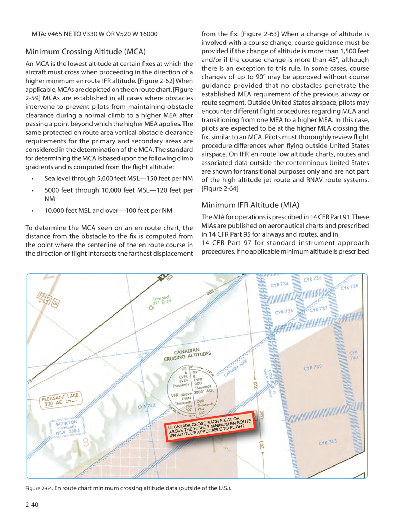Figure 264: minimum IFR altitude, MIA. The MIA for operations is prescribed in 14 CFR Part 91. These MIAs are published on aeronautical charts and prescribed in 14 CFR Part 95 for airways and routes, and in 14 CFR Part 97 for standard instrument approach procedures. If no applicable minimum altitude is prescribed